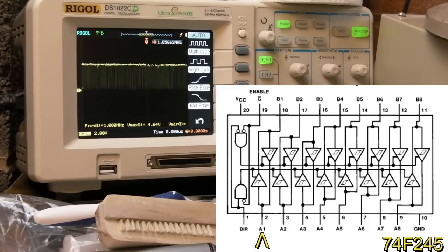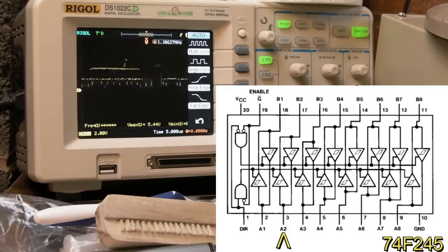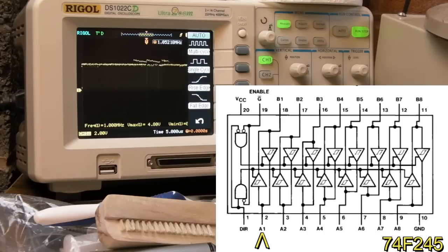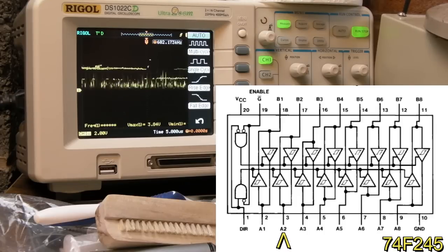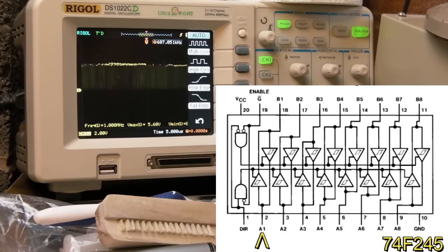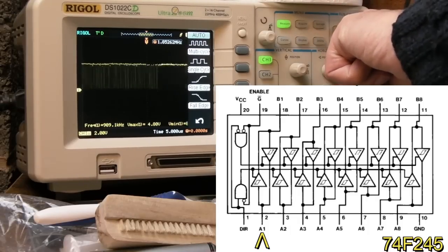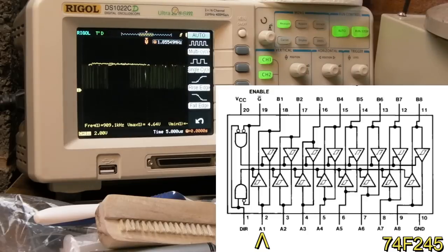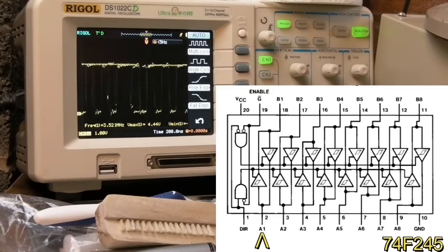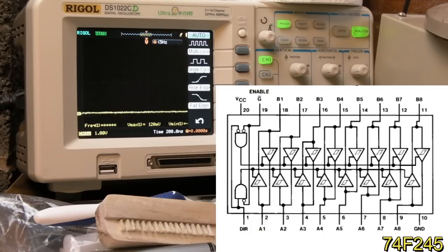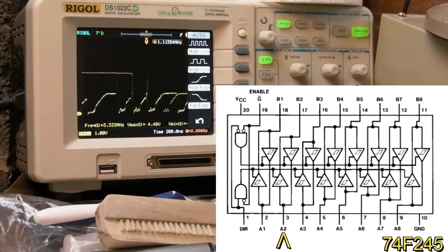Then if I look at pin 2 on the 245, this is where it comes out. Look at the logic level there. Let me compare it to pin 3, which is another data bit. Just swapping between them, that's pin 2, that's pin 3. Yeah, they look different, I think. Let me hit auto and see if we can get a cleaner view. It's peaking around 4.3, 4.4 volts, but again there are some shifts in logic level. Look at pin 3, see how different that looks.